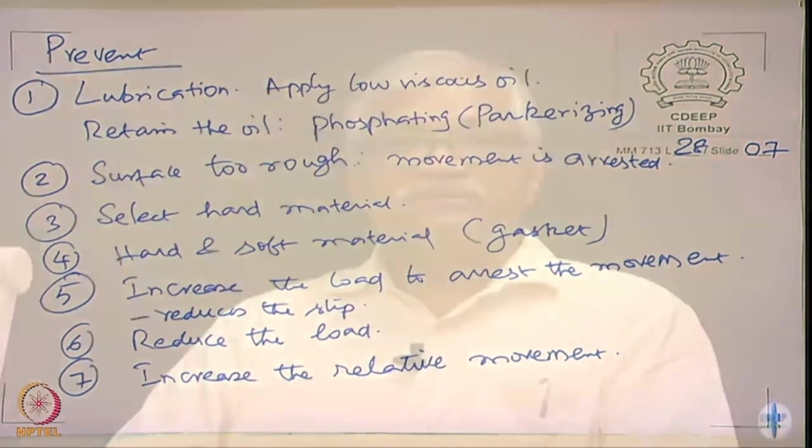Any other questions? So can we do this grounding, that is active shaft grounding? Shaft grounding you were talking about in ships, right? Yeah, that is called active shaft grounding. That probably is to reduce signatures that happen there, and also to reduce what you call stray current corrosion that happens in the shafts, right?